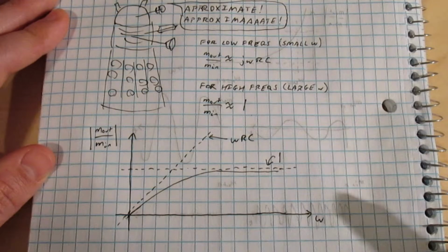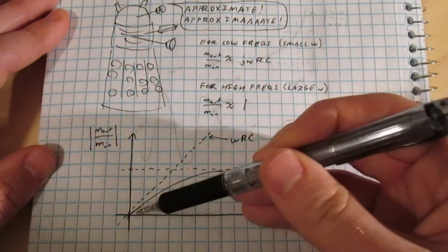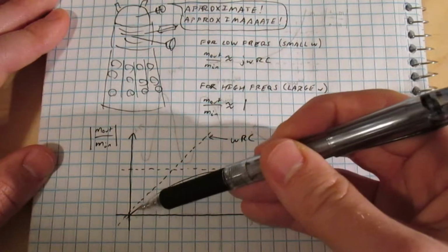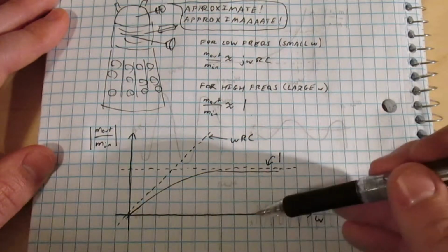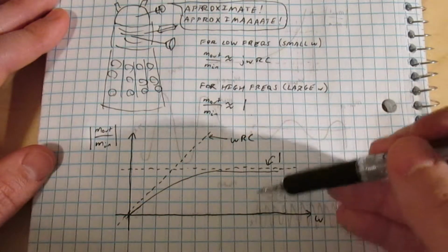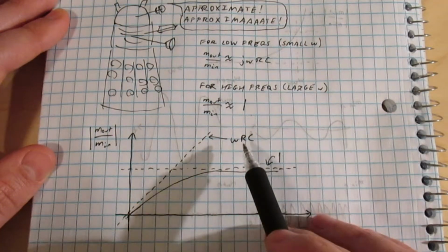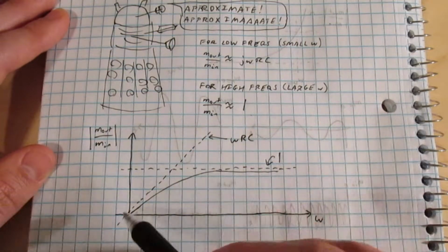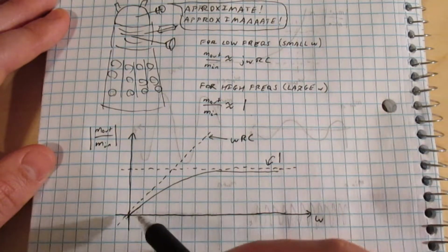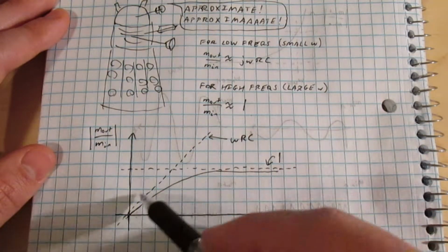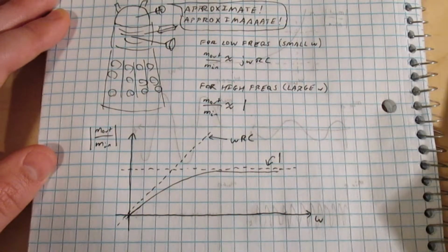And from looking at this, you can see how it corrects for the DC offset. So for really slowly changing signals, and signals that don't change at all like DC, we can see that we have a really low gain, so those don't get passed to the output. But for a heartbeat signal which changes a bit more quickly, we have a gain of about 1, so that does get passed to the output. And by changing RC, we can change the slope of this line here, which changes how steep this part of the curve is, which changes how quickly it will track out that DC offset.